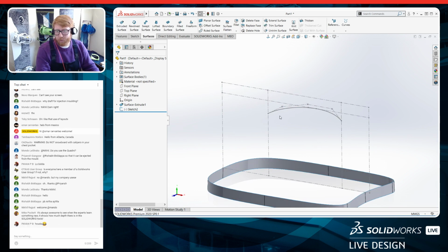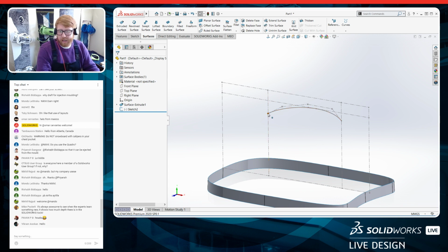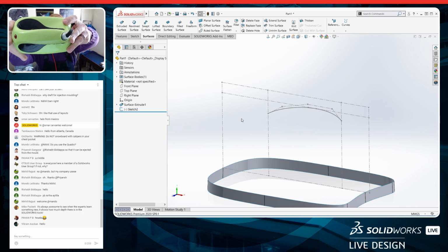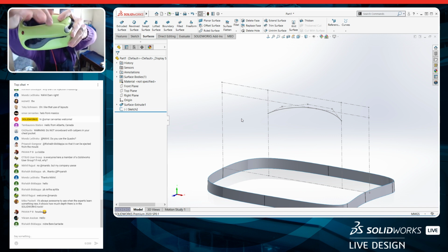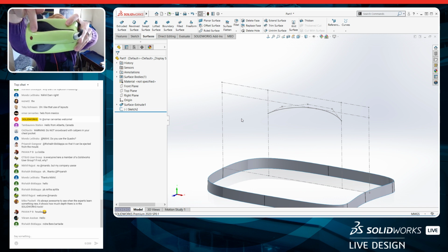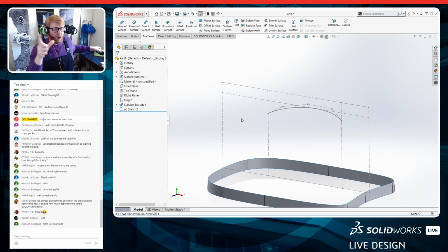Right now, I could just put a plane at the end of this point and sweep the shape across. Now, that sweep shape that I'm going to use is an ellipse. However, if you look at this handle, it actually gets wider, right? Like it's wider right here than it is right here or back here, right? So I need that thing to get wider as it goes, but it's the same height, right? It's the same height the whole way through.